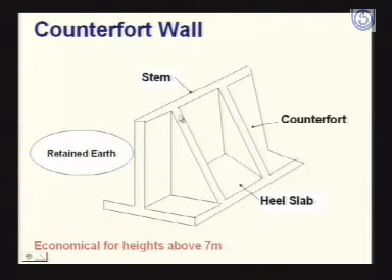And for this stem, you can see that the predominant direction of bending and flexural reinforcement is now horizontal, whereas in the case of the cantilever wall the predominant direction was vertical.